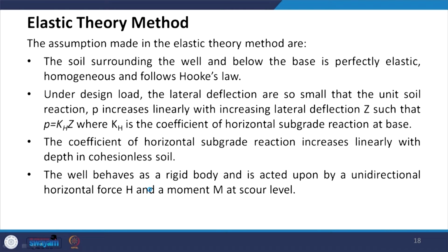Under design load, the lateral deflections are so small that the unit soil reaction P increases linearly with increasing lateral deflection Z, such that P is equal to Kh into Z, where Kh is the coefficient of horizontal subgrade reaction at base. That means if you increase the value of Z, the value of P is going to increase. Kh, the horizontal subgrade reaction, also depends on the type of soil. If you have sandy or granular soils, the value of Kh is normally considered to increase linearly with depth; this coefficient of horizontal subgrade reaction increases linearly with depth in cohesionless soil,